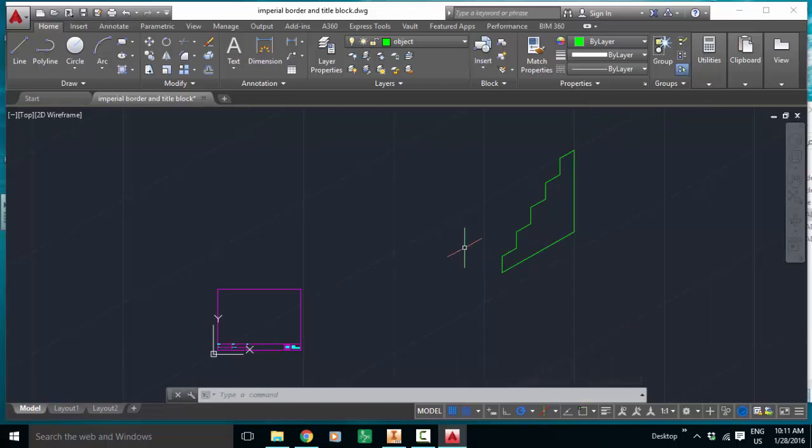Let's go on to our left. So we're going to hit F5 and toggle to our left, which changes our grid. Or we could go down here and we could switch to isometric drafting, isoplane left. So now we've got to fill in our shape. So we're going to go from our endpoint over this way, a distance of 10.